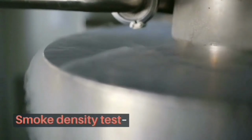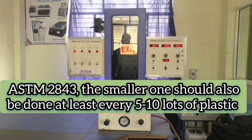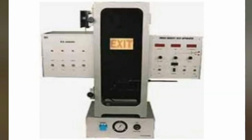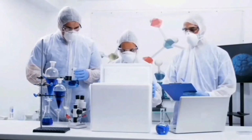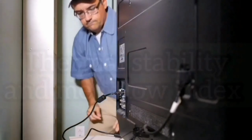Smoke density test ASTM E662, the smaller one, should also be done at least every 5-10 lots of plastic. This is important to know at the input itself if your compound passes the regulatory requirement or not.